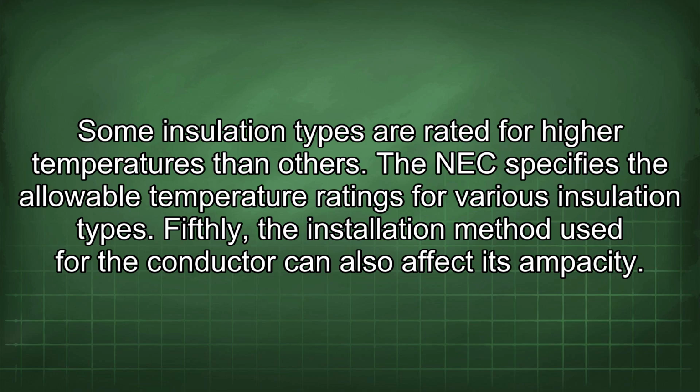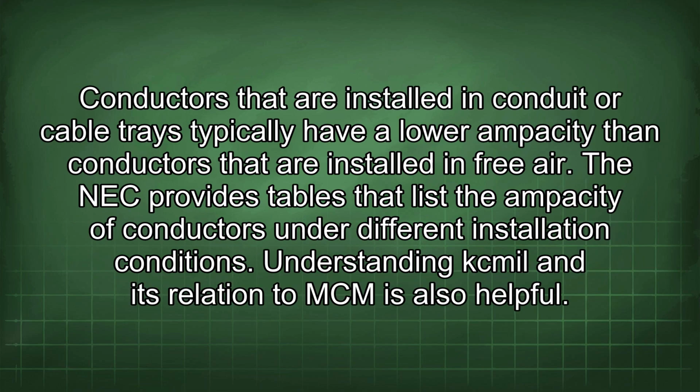Fifthly, the installation method used for the conductor can also affect its ampacity. Conductors that are installed in conduit or cable trays typically have a lower ampacity than conductors that are installed in free air. The NEC provides tables that list the ampacity of conductors under different installation conditions.